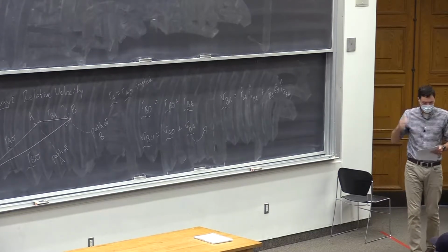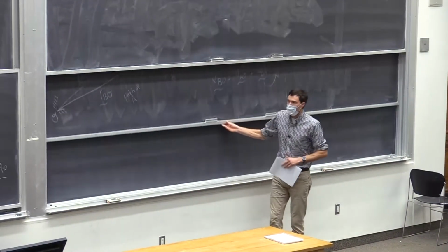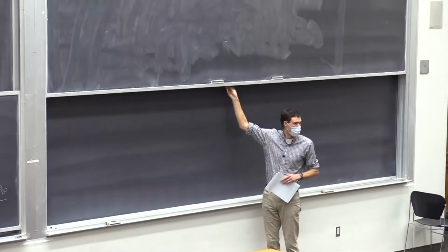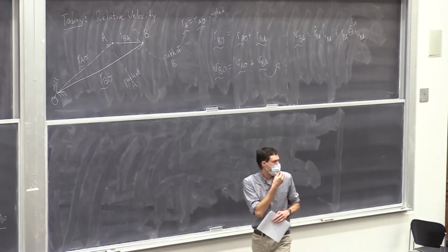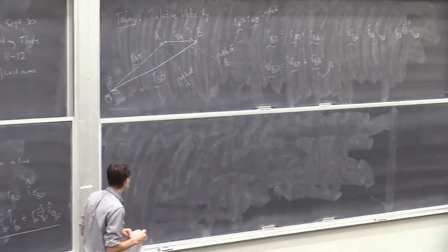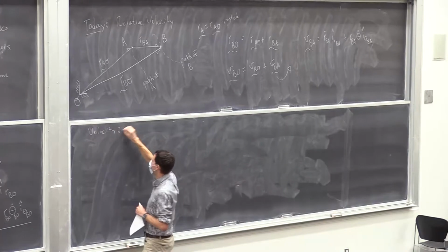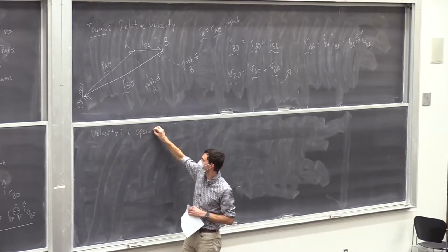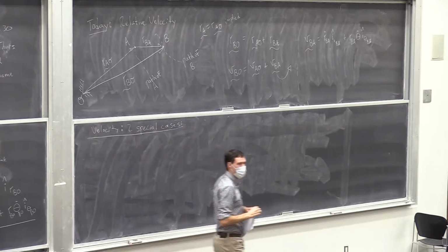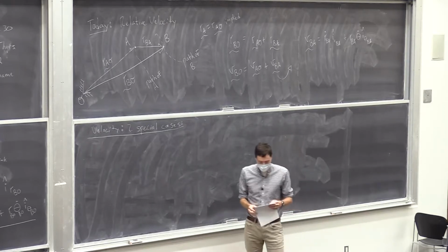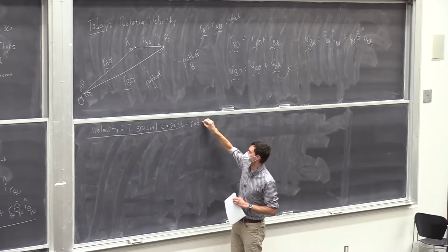I want to do it nice and careful like this, because now we're going to start attaching those to the links. And in fact, I'm going to identify two special cases for links. And it's going to become clear why this radial transverse coordinate set is really handy for real mechanisms with linkages. Okay, so these are our two special cases. This won't allow you to analyze every mechanism component, but it'll allow you to analyze many. And these are special cases when we're using radial transverse coordinates.